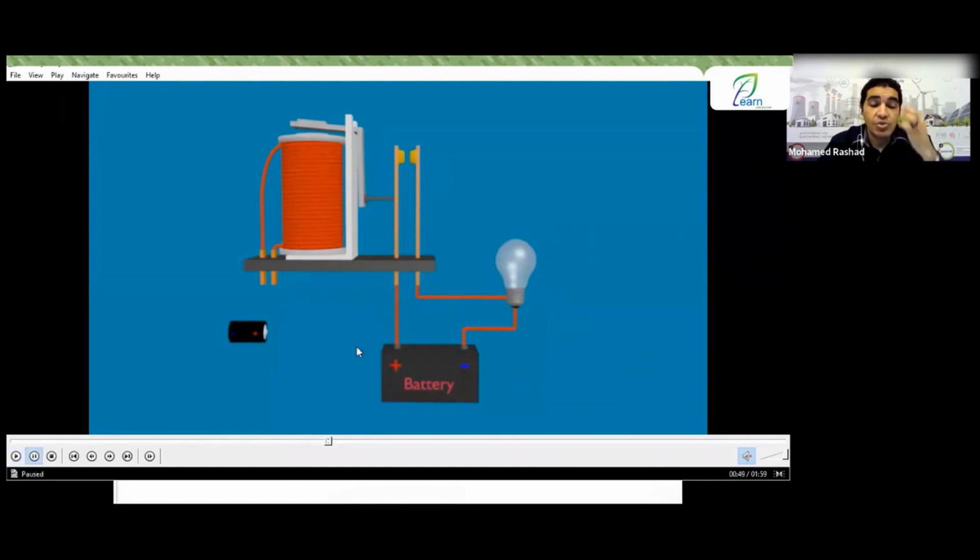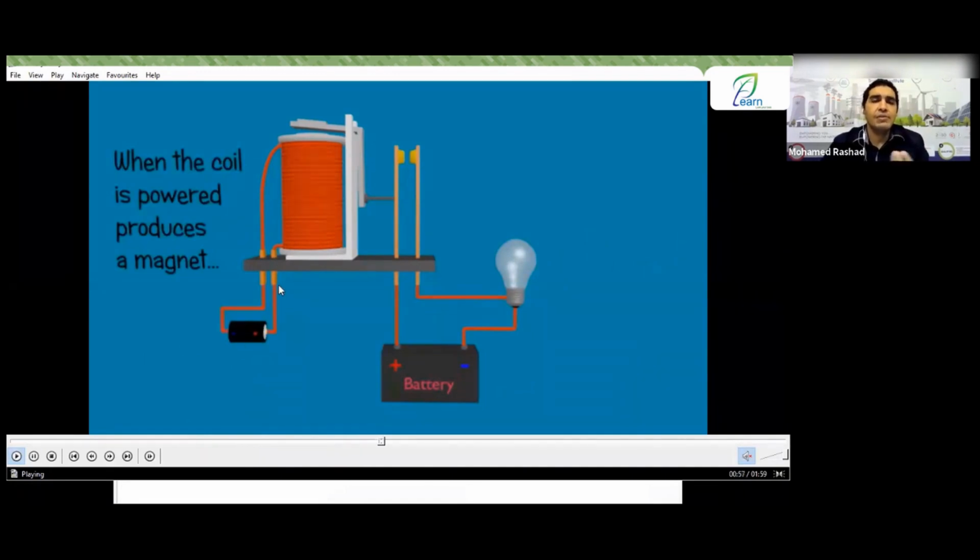Okay, so what did he do? He now brought a battery here. This coil draws a very small current. When you connect this DC battery, meaning positive and negative, to the coil, or AC, since our control circuits are all in the switchgear or in GIS, whether medium or high, or even low, it actually operates on DC. Of course, sometimes you find circuits that operate on AC. The important thing is that when you apply voltage here, this coil gets energized, or becomes magnetized.